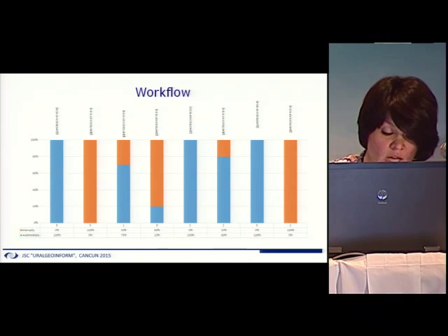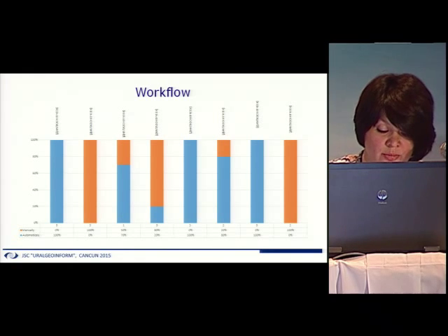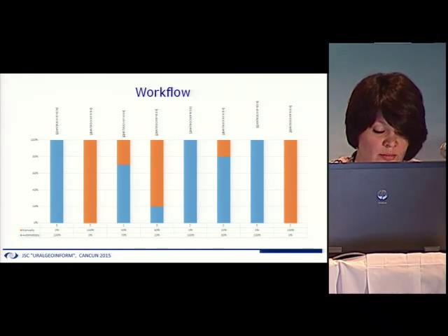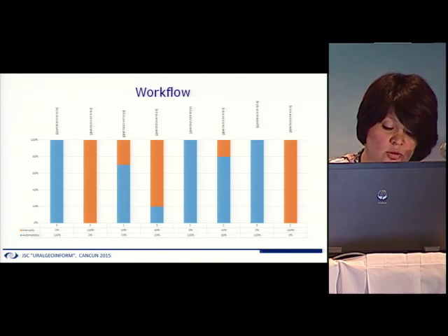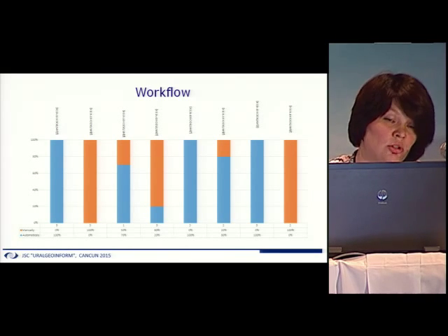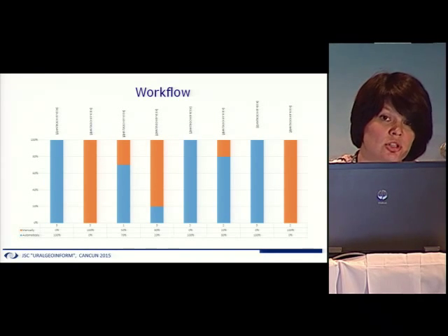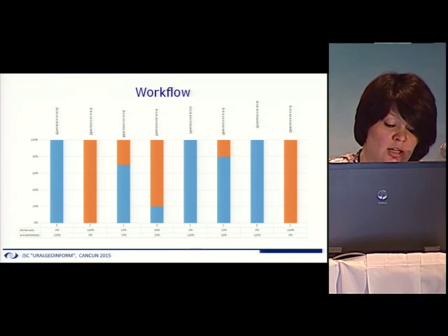Since our blocks were relatively large, we assumed to rely on BC coefficients and to use as few GCPs as possible. We found that we had to set a redundant number of points to meet the required range.